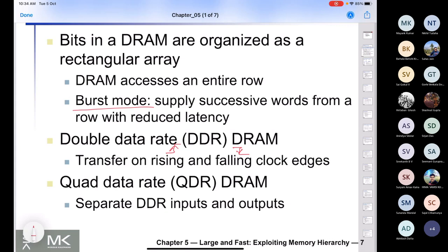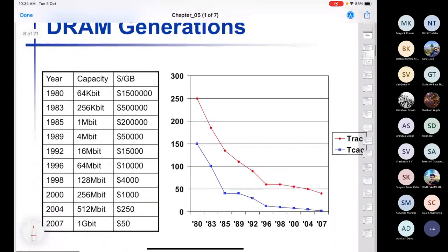So in that case, you can perform input and output operations, of course on different address ranges, through two separate ports, and each of these ports works at both the positive clock edge as well as the negative clock edge. So overall you have 2 into 2, a factor of 4 throughput, basically.